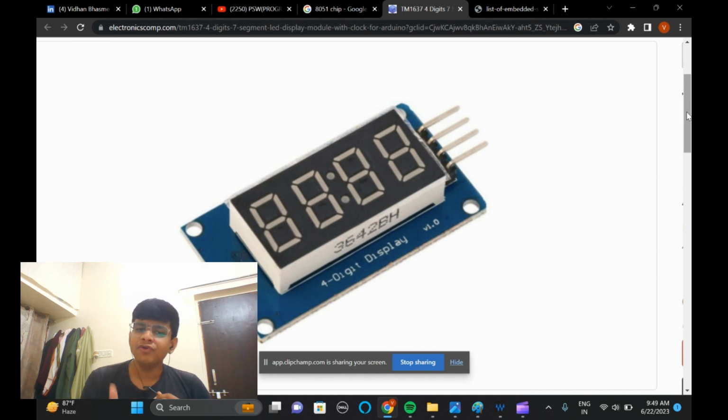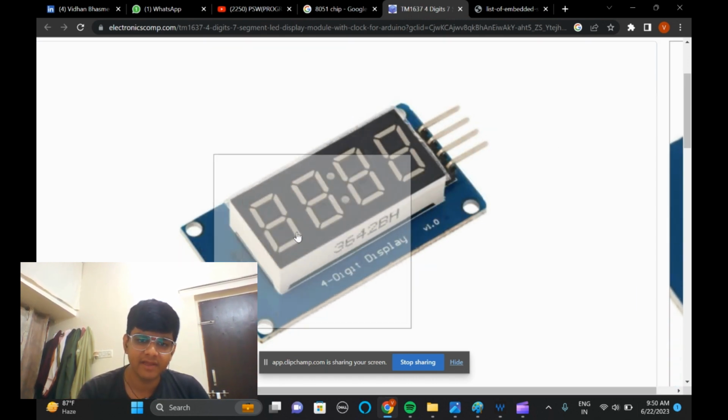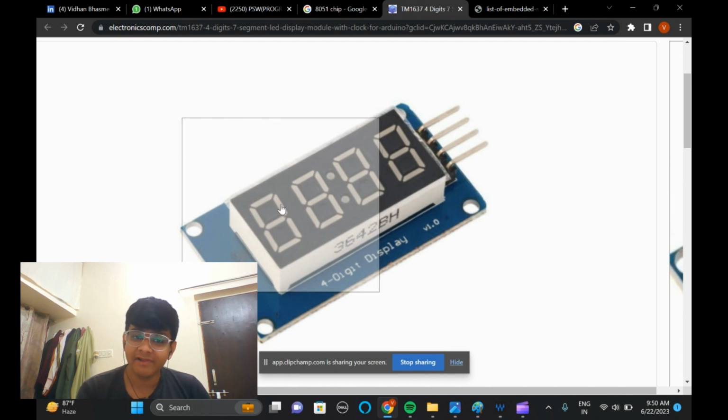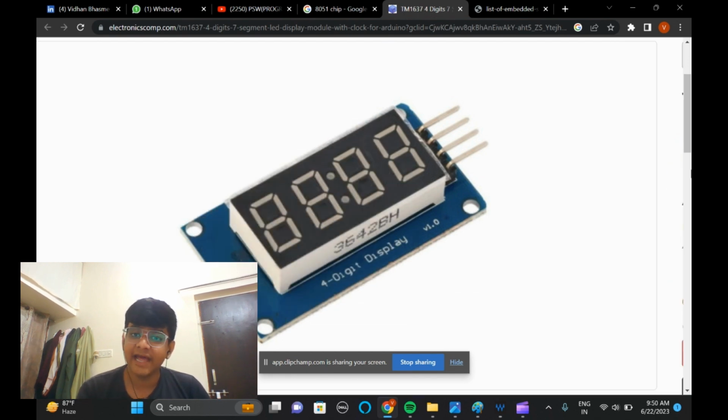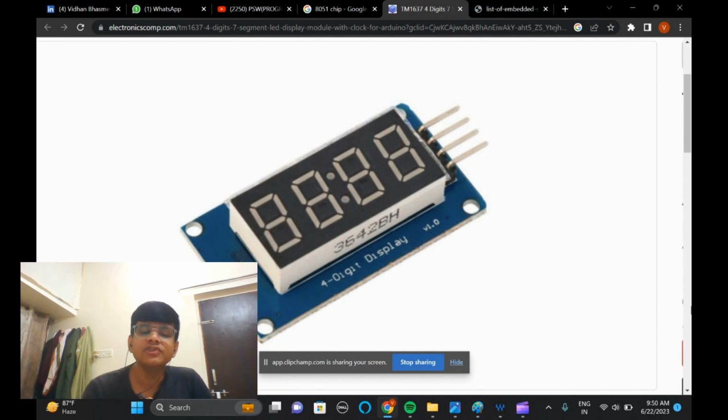If I want to show one on this digit, I should enable this line and this line, because there needs to be some code that will enable only these two lines. That code is nothing but data, which must be permanent. So for one there must be some data telling which lines to display. I think you are understanding. Such codes are called permanent data, and they are stored in ROM in the form of lookup tables.